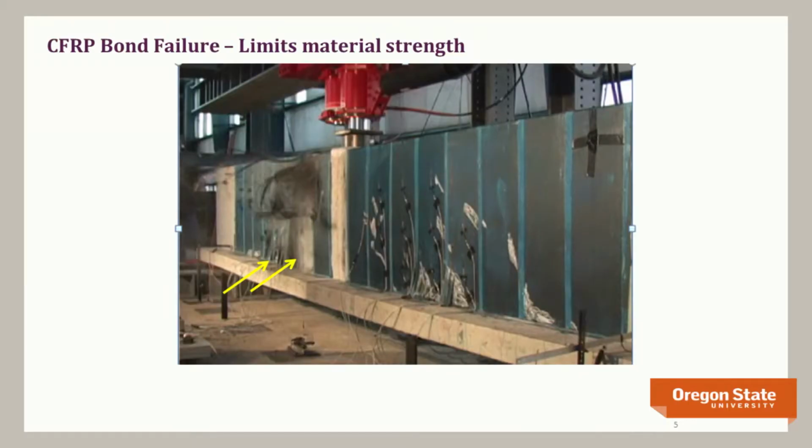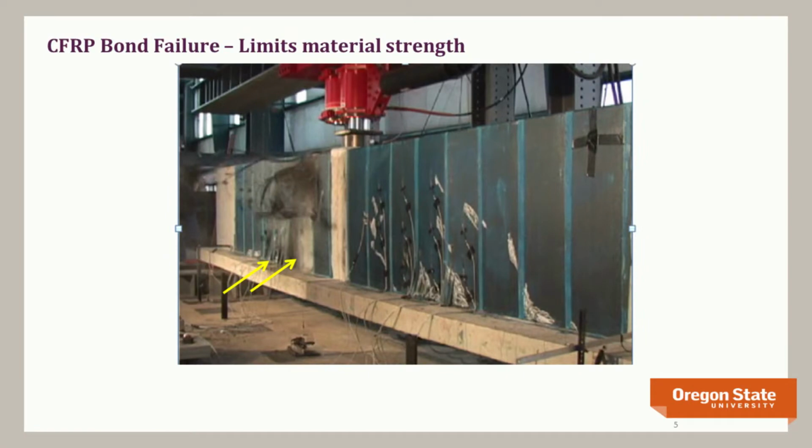We've done a lot of work with carbon fiber, both surface bonded as well as pre-cured laminates, and this is a screenshot of a failure of a surface bonded carbon fiber sheet. And you can see all those white marks there are debonded regions within that beam as you're nearing capacity. And at the ultimate capacity, you're essentially rupturing the bond strength. And you can see in the picture there, the carbon fiber is actually tearing off the surface, exploding off the surface.